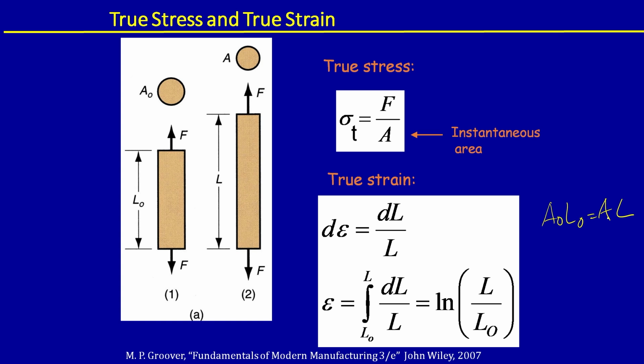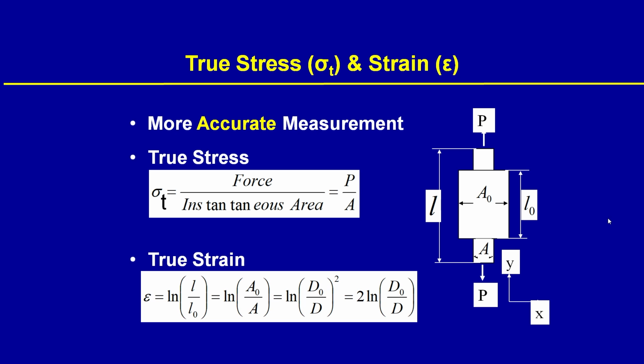So, this is the difference between true stress and true strain vis-a-vis engineering stress and engineering strain. Please keep in mind these definitions are very important, because true stress and true strain can be used when you process materials using deformation processing. Engineering stress and engineering strain are used for design of any component. If you want to use any material in actual application, what kind of parameters will you be using? Yield stress, UTS, original length and original area. One can actually convert, or one can get a relationship very easily, from true stress to engineering stress and true strain to engineering strain.